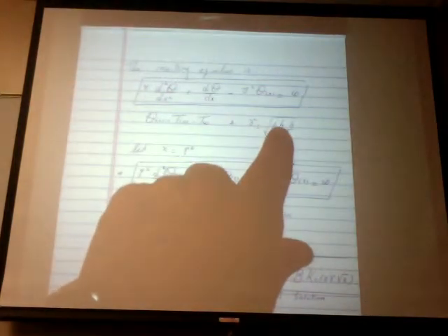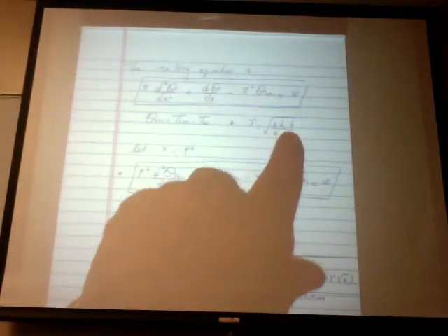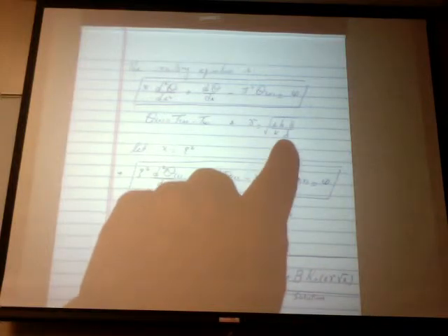We put gamma right here. It contains convection coefficient, the base of the fin, the conductivity, the height of the fin. So geometric, convection and conduction information is all embedded into gamma. So a simple problem such as heat conduction in a fin like that in a triangular section, the solution is in terms of Bessel functions.